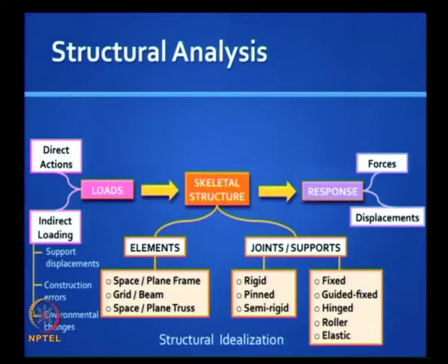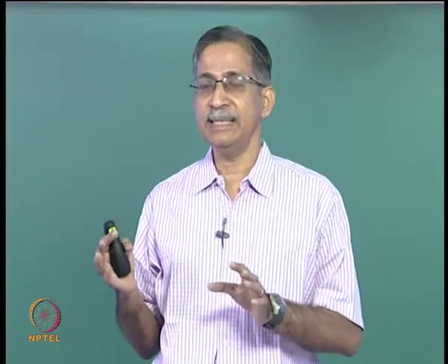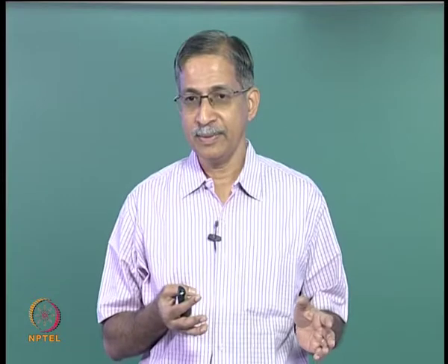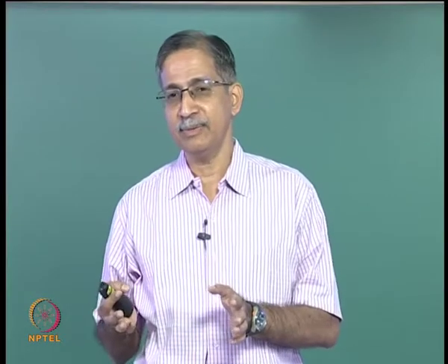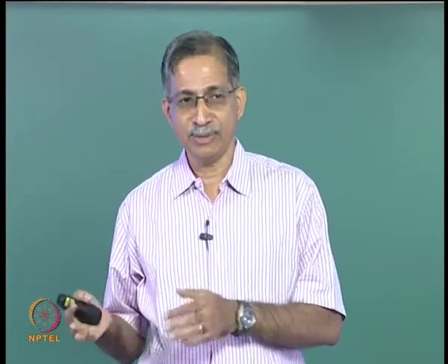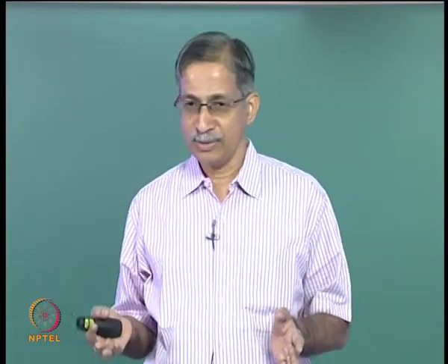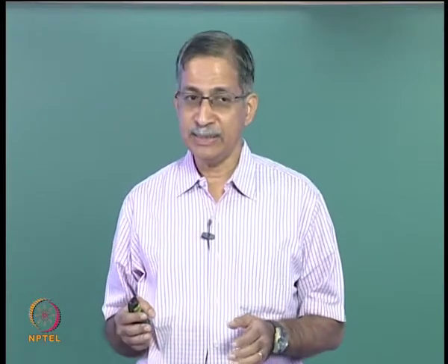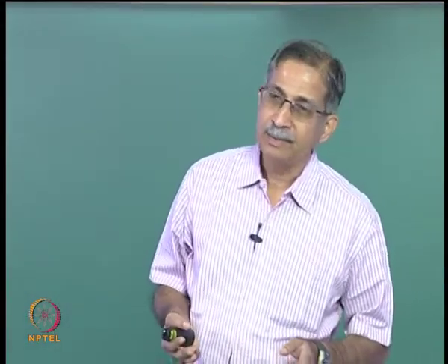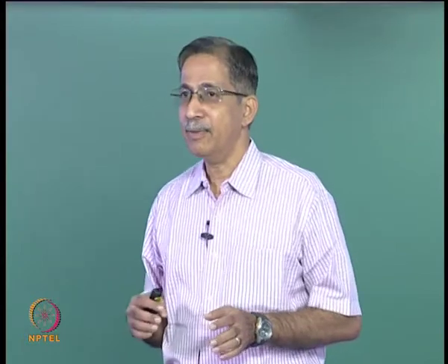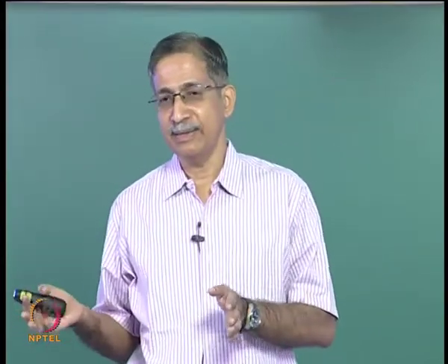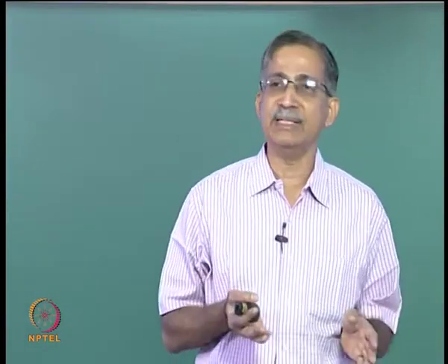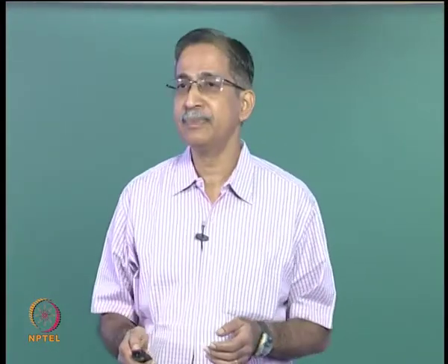So if you look at the structure in its entirety, you have 2 fields. You have the force field. Some of the items in the force field come from the loads, which you know, but many of the items you do not know, and they come from the response. They include the support reactions and the internal forces, and you also have the displacement field, which is related to the force field. Most of the displacements are unknown, so they are in the response side, but sometimes displacements come as a kind of indirect loading, so they come to the load side.